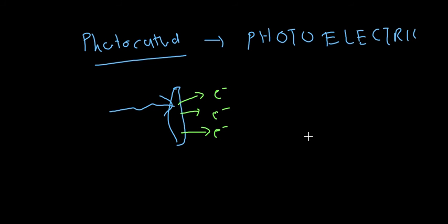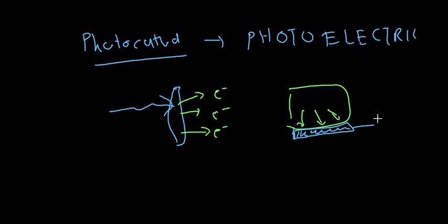The same principle appears here also. From the scintillator, you will have light photons. This actually falls on your photocathode. Proportional to these light photons, the photocathode will emit electrons. That is the purpose of your photocathode.